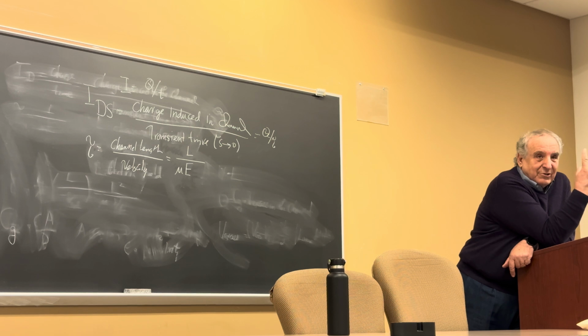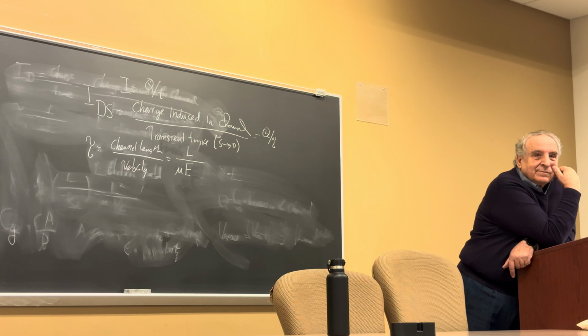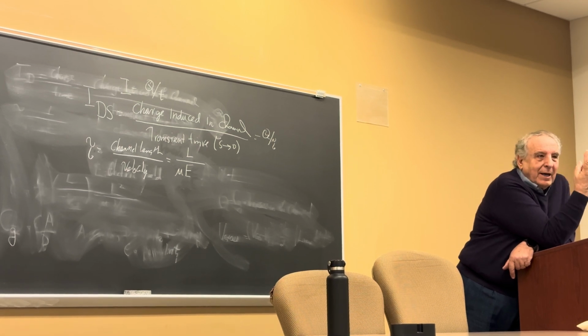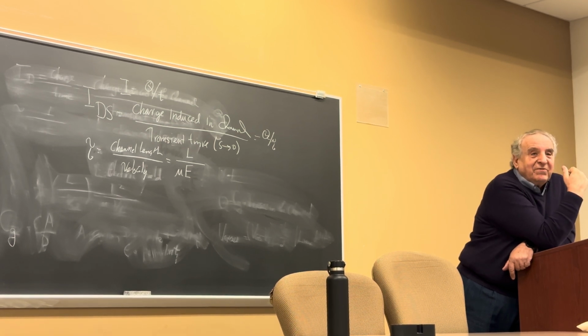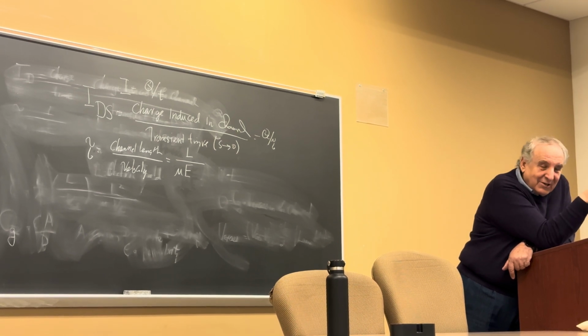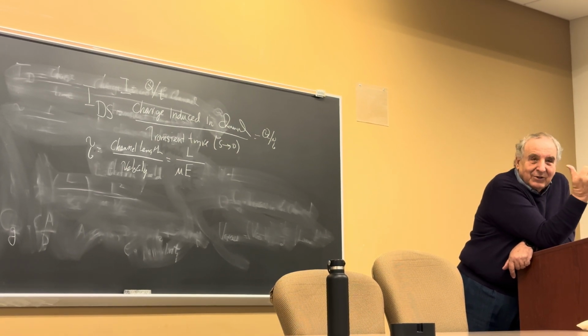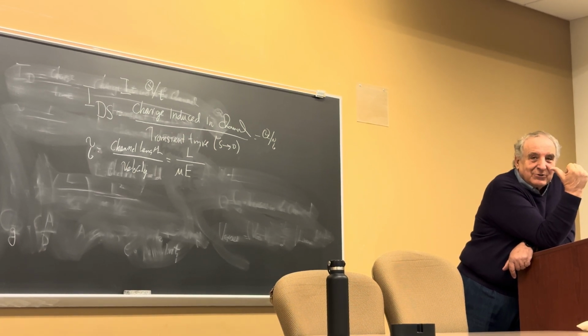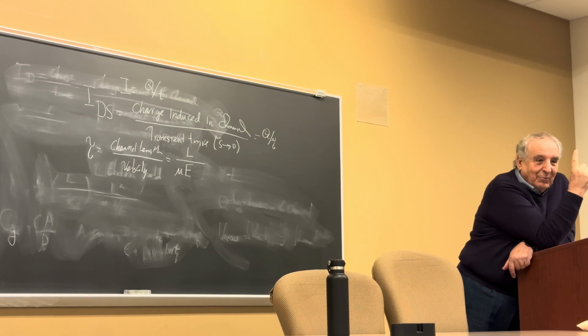What else affects mobility? I told you one, mass. What else affects mobility? Energy. Charge density. Temperature. Why temperature? Because that's the average movement speed. More heat, more collisions. That is a perfect answer. If you raise the temperature here, and we all want to get out of this room, we start pushing each other to get out. None of us will get out because we start colliding with each other. More heat, more scattering. It's called scattering, collision.